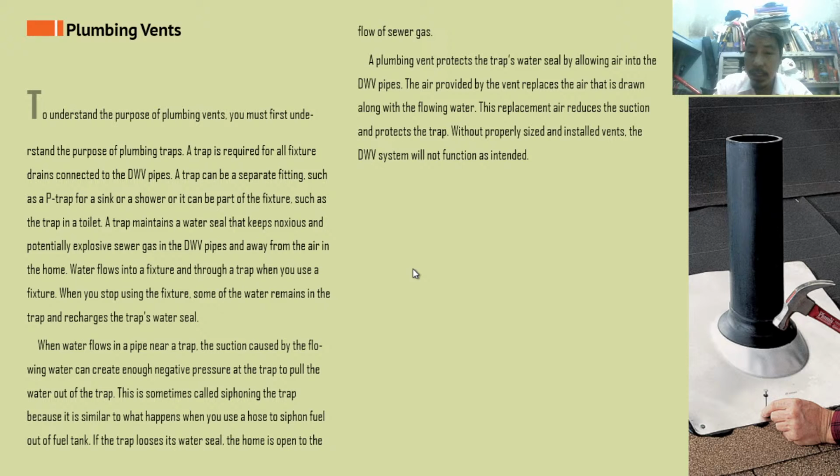So we have to maintain the water seal. If the water seal is broken, all of the water will flow to the drain pipes, and thereby the noxious air and potentially explosive sewer gas would be present in the toilet and bathroom.